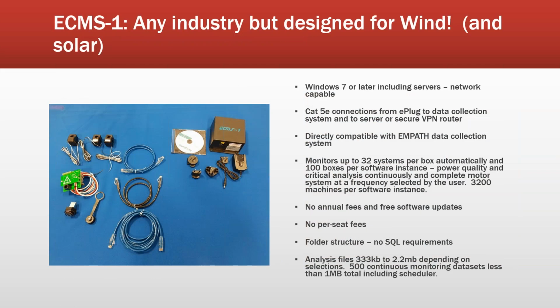By the way, as an edge system, what's kind of cool is that the people who have the device, you own the data. So it can be kept locally, it can be kept remotely, it can be kept both. You can do the analysis on site, it can be subcontracted, or even we could do it. So there's a lot of flexibility in the system. This is an ECMS 1. There's more CTs available than these, but if I'm on the low voltage side, I can put these around the leads coming from a CT and I still have accurate data.